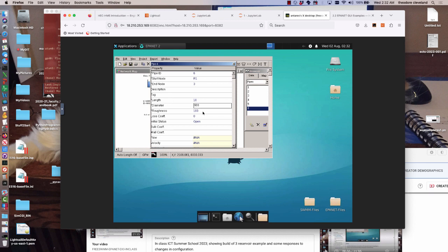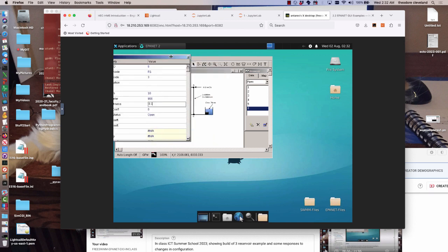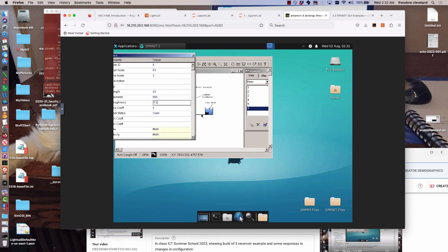And we'll keep our roughness. Okay, so it's very short pipe, basically 10 meters long, a meter in diameter. So it's as if that reservoir is directly connected to that point. There's no head loss in that section of pipe. We'll do the same here. Now, in a real analysis, if you actually know the dimensions of the connection, by all means use them.